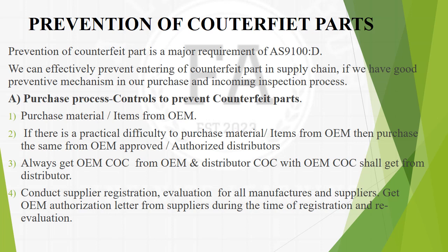If you are purchasing from an authorized distributor, since the OEM is approving or authorizing these distributors, there is less chance of counterfeit parts. Another way is to get the OEM COC and the distributor COC from the distributor. That is another way to control counterfeit parts.